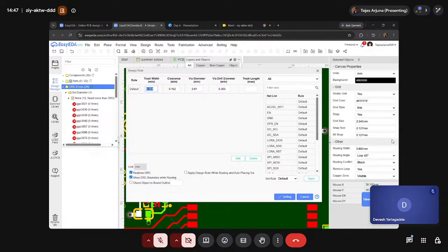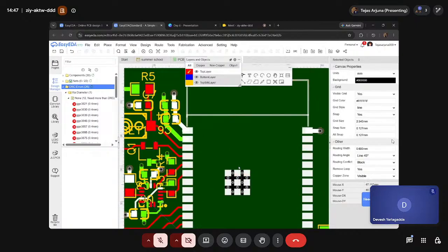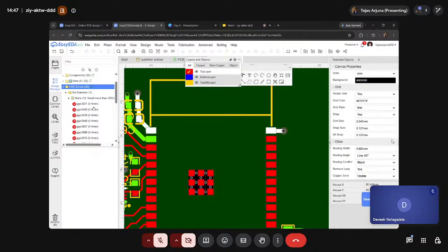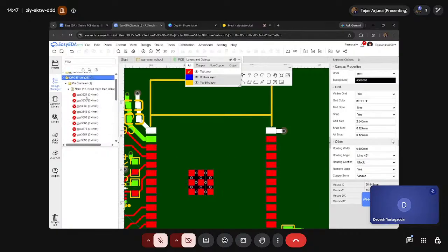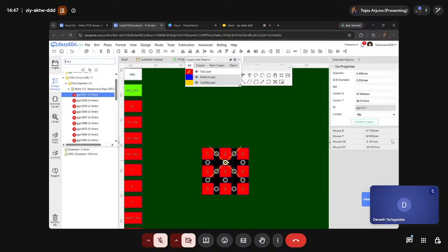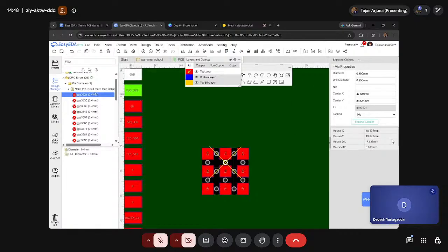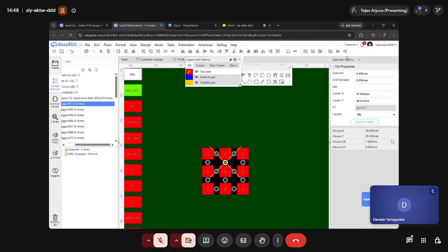For the specific manufacturer, according to the manufacturer, we have to use the design rule, and if our PCB layout has some mismatches while routing or placing wires, the design rule check will put forward those things. So the wire diameter and the hole size are small. So what we'll do, we'll increase it. That's it. Increase it to how much? Minimum 0.61. We'll put 0.62. And this to 0.31.